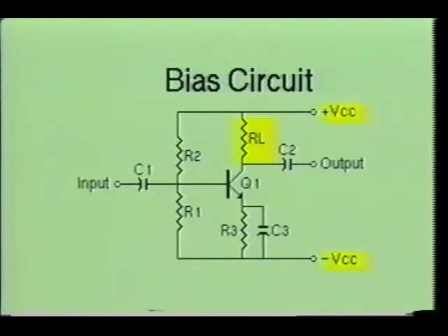The load resistor, RL, which is attached to the output of the amplifier along with the power supply, is used to set the power output limitations of the amplifier. The output signal current cannot exceed the power supply voltage divided by the load resistor.